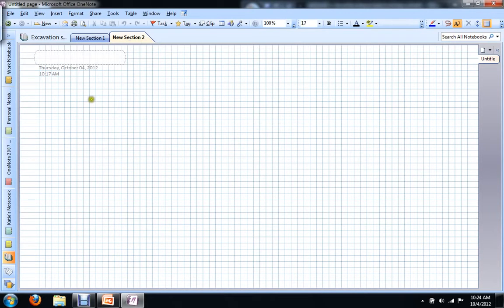Let's say we have a solid, and I'll draw this out as a solid block. If we have a solid and we apply a force, say with our hand here, we'll call that sigma z. If this is a solid block of rock, how much of that force is going to translate into sigma x? Meaning, how much of our vertical pressure from our hand pressing on this rock is going to transfer into the lateral direction? Well, the answer is almost none, or practically none.